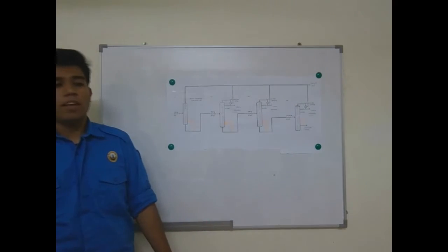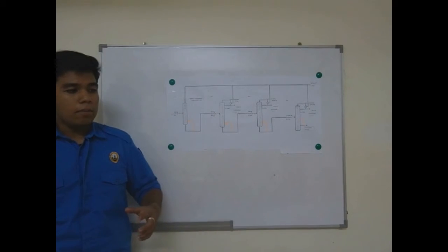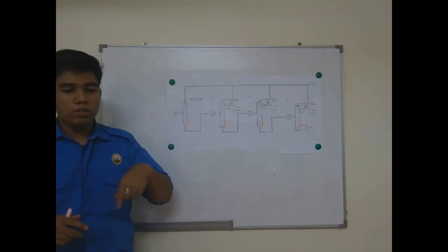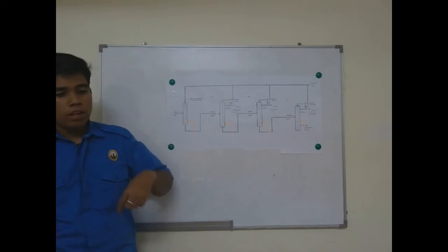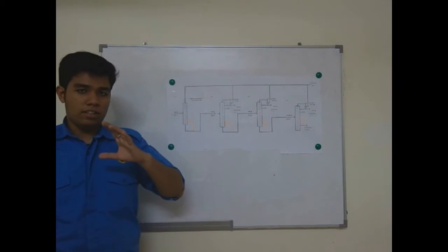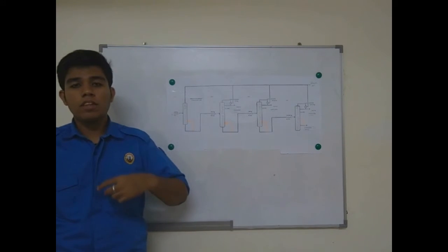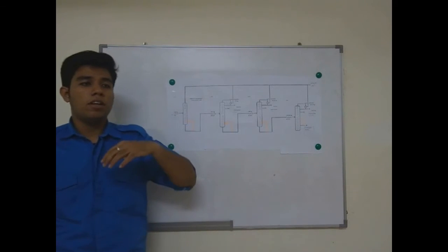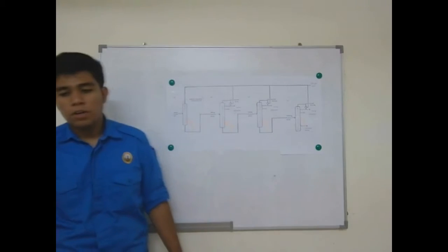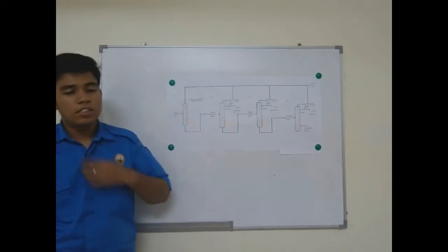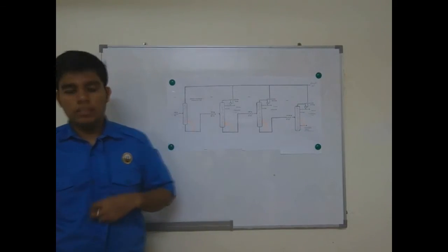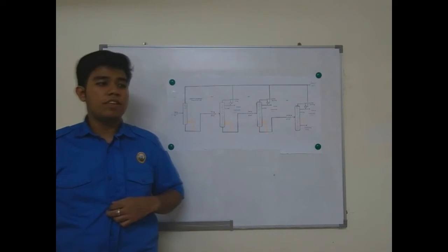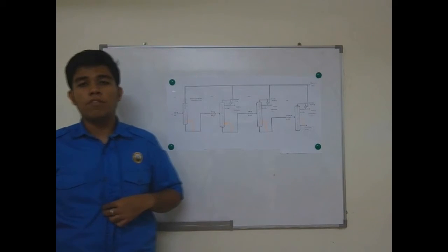Third and last, for this design equipment, we should use a smaller diameter separating column, meaning the diameter of the column will be smaller than the usually used. This is because when the product is in the separating column, it requires a certain temperature to be split from the triglyceride. As I mentioned earlier, a larger diameter is not as good as a smaller diameter because a larger diameter has a larger surface area in contact with air.